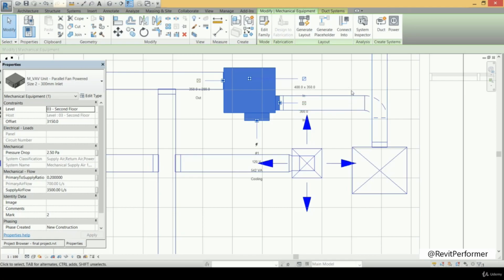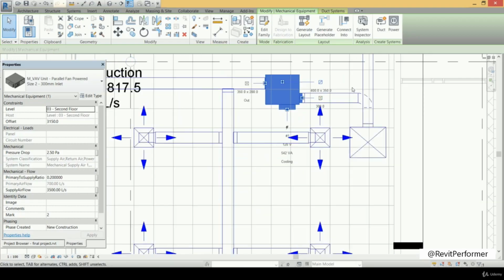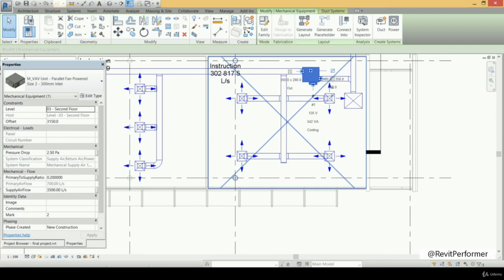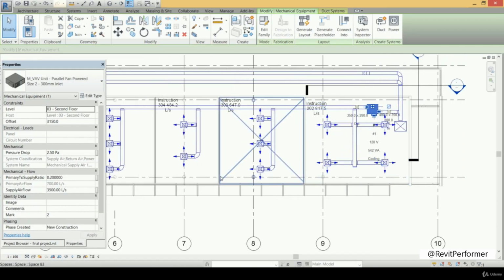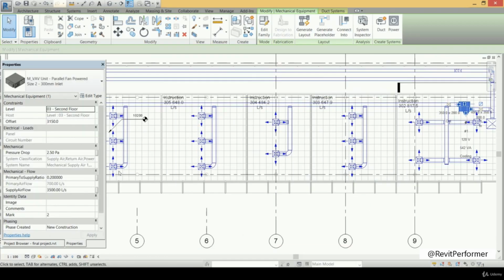And for that purpose, we need to make the usual trick, which is to increase or decrease the offset of the return duct. So if we change the offset of the return duct, generally we will have no problem as it will not interfere with the supplying duct. And the plan that we have now for routing the return duct is to go out of the VAV box with a duct in that direction, then we go in that direction here, and then we go forward in that direction to feed all of the spaces that we have.